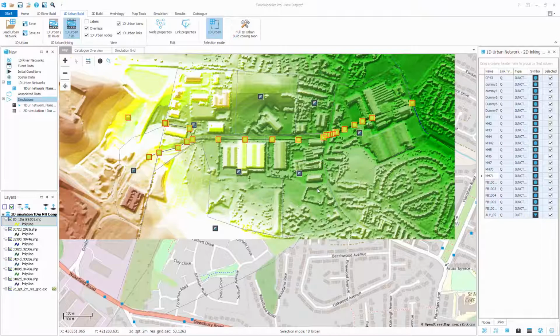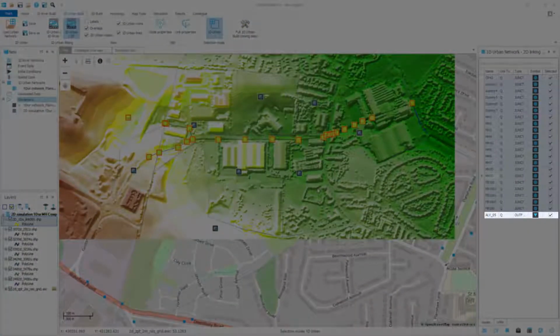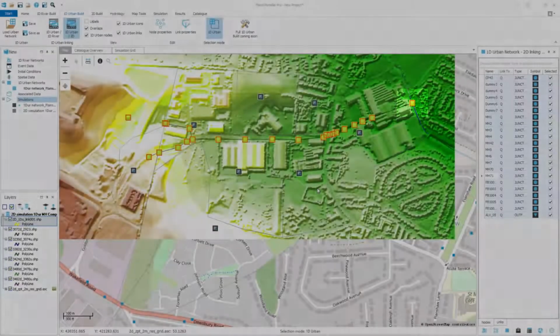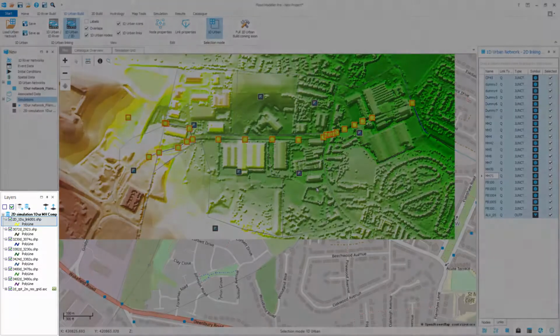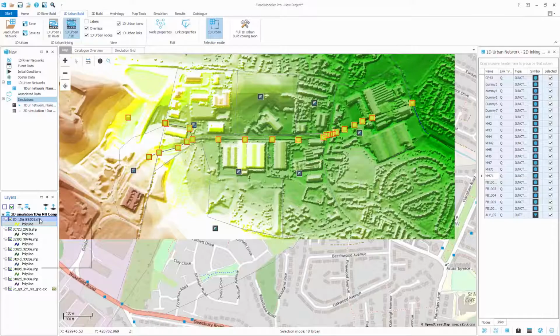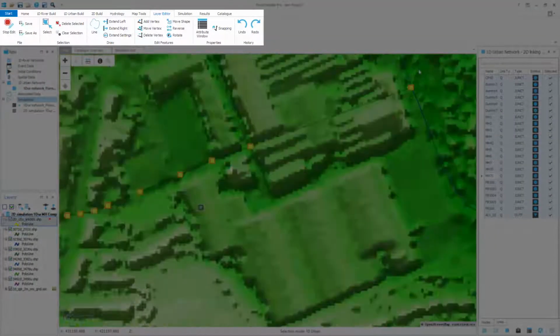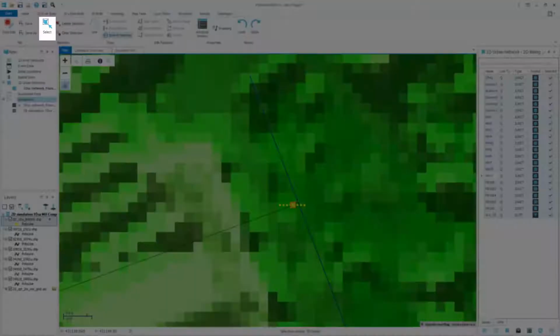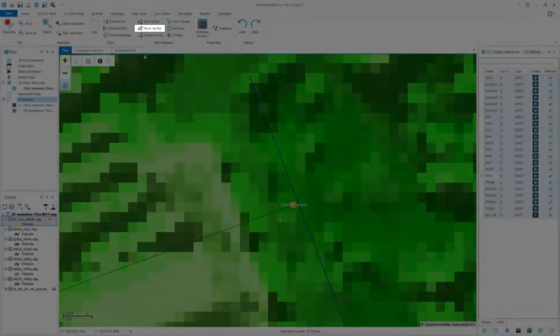We are now going to edit the link of the old file. We will change the coefficient it shares from 1.2 value to something less conservative, and we will change the orientation of the line to be orthogonal. Select the link shapefile on the Layers panel. Right-click and select Start Edit. A red star appears next to its name during the edit mode. The new layer editor will open on the top bar. Zoom to the old file link, use the Select tool to select it, then use the Move Vertex tool to move it and place it orthogonally.